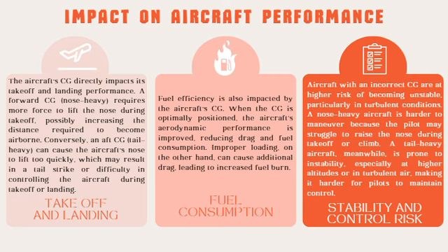Fuel consumption. Fuel efficiency is also impacted by the aircraft CG. When the CG is optimally positioned, the aircraft's aerodynamic performance is improved, reducing drag and fuel consumption. Improper loading, on the other hand, can cause additional drag, leading to increased fuel burn. Stability and control risk.